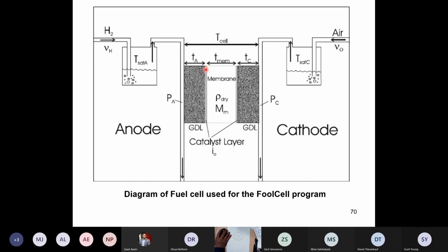And the catalyst layer is here where my laser's moving along. So there's a difference in the hydrogen concentration. Well, actually no, because it's pure hydrogen. There's a difference in the moisture content from the front to the back. It will generally be more moist at the back and less moist at the front because there's osmotic drag dragging the water molecules along with the protons from the left side to the right side. If you have extra hydrogen, it will be exhausted out the bottom.